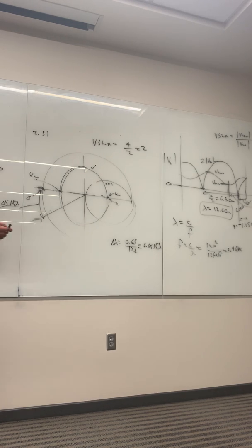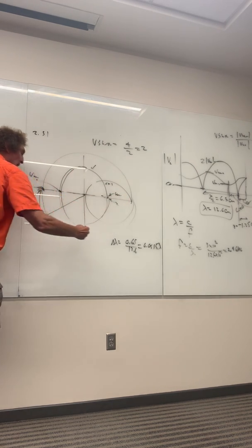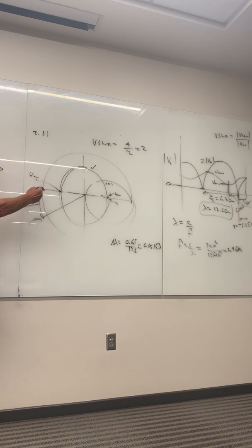Now what I need is this point in terms of wavelengths towards generator. So if you think about that, 0, 0.25, then it's 0.5. Start with 0.5 and subtract 0.0515 from it. What do you get for that mile marker? 0.4485.